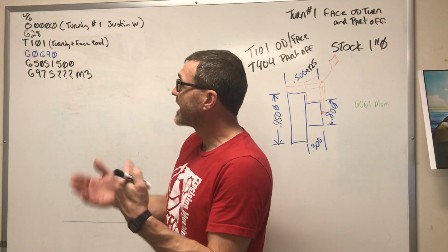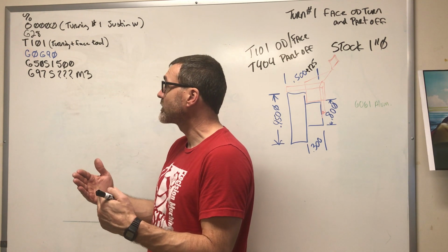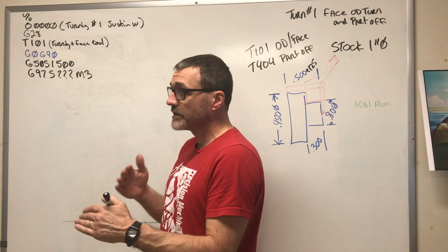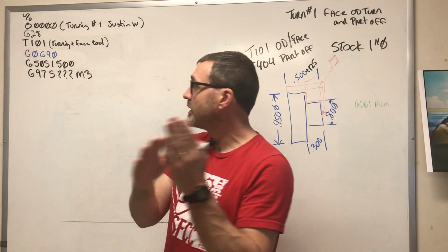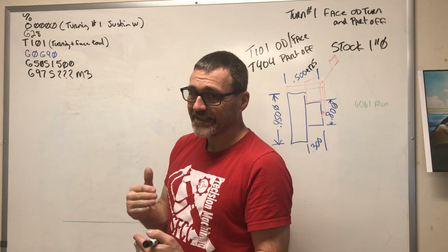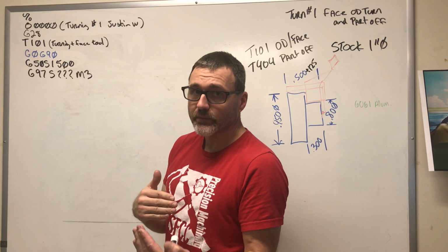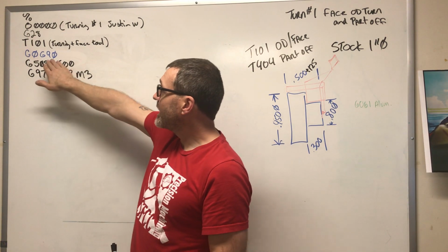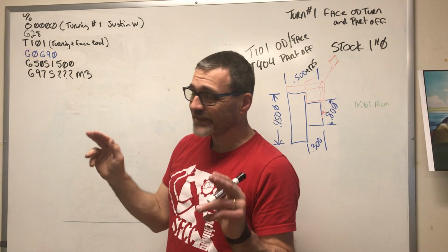The only time that those are not going to be like that when you start up your program is if you ended in a G1 move, which is typically not the way that we do it. We normally rapid home. Or if you're in an incremental move, which we're typically not ending in, even if we're running in an incremental movement, we're going to end in a G90. So I went ahead and put those in there just for safety's sake.